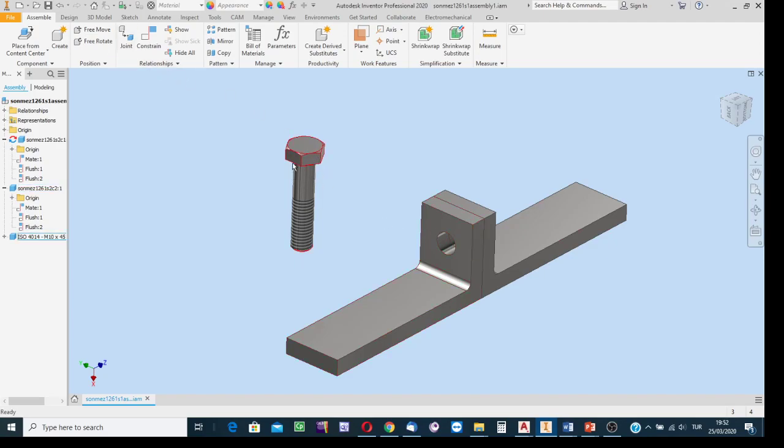But I see here the length of the stem is longer than the necessary order. 26 plus 10, 36. But the length of this one is 45. There will be an unnecessarily extended part. So I'm going to delete this bolt. I'm going to try the other standard bolts.